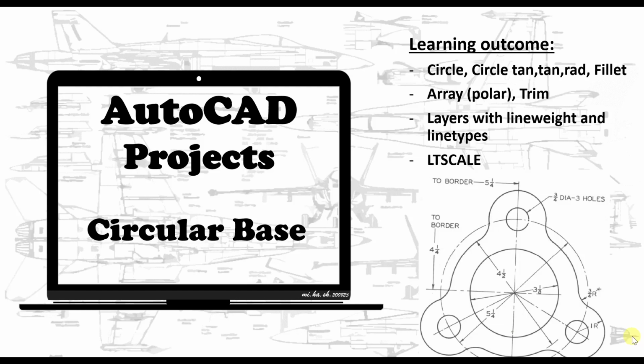Welcome back everyone. In this video we're going to be drawing this circular base. We'll be covering circle, circle with tangent radius option. Also we're going to talk about the fillet command and how we can utilize that.